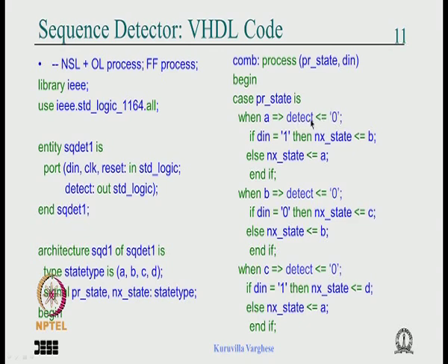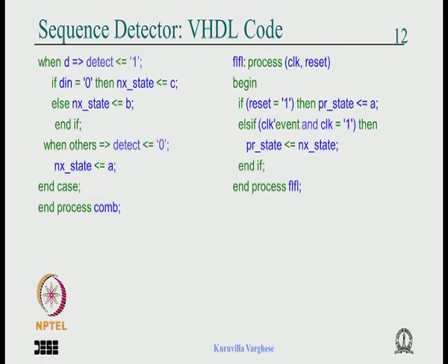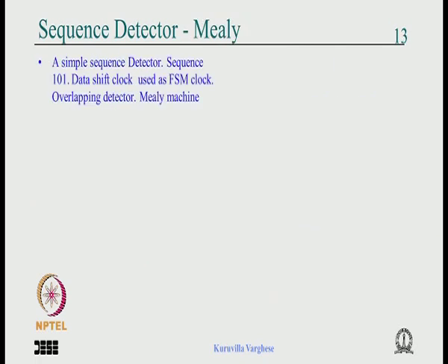And when it is Moore there is no condition on it. When it is Mealy you can write a simple logical condition here if it's a simple case, or you can use if or case or whatever is appropriate to use at that point in time. The flip flop is the same.